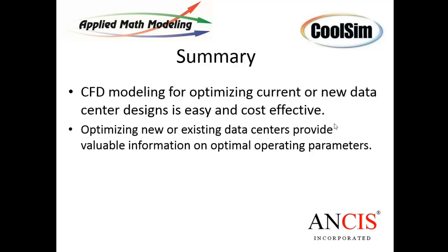You run a CFD and you compare it against the values measured by the sensors to see if the CFD calculation is predicting what you're measuring. Did that come through clear? Is that okay, Magnus? But in terms of measurement, we don't use measurement. We use it to calibrate the model and correlate the model, but not as part of the model.